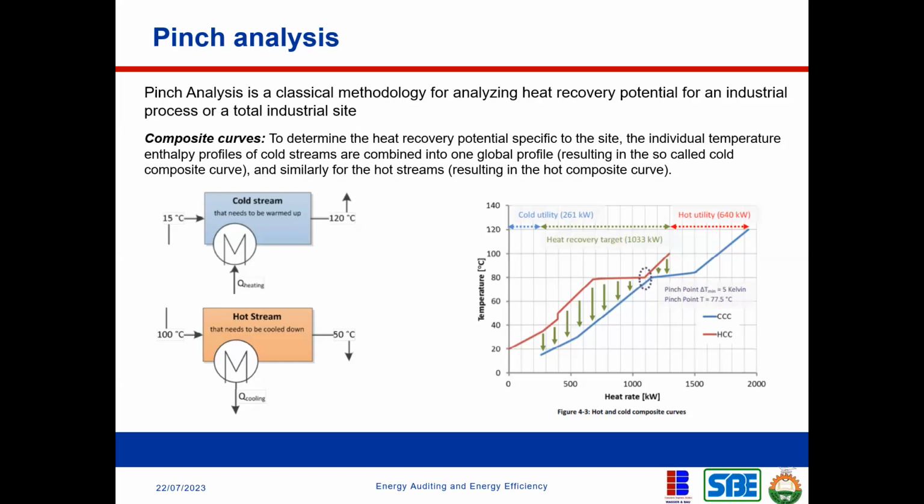So, for example, if you go to a yogurt producing company, if they want to do pasteurization, they will add heat. But after the product has been produced, they will need to remove heat to bring it to a low temperature, right? So, in this kind of situation, there is an opportunity such that when you're removing heat in your cooling process, you could just transfer that heat, more like transport that heat, into the place where you need to add heat. So you don't waste that heat and then generate another heat to add.